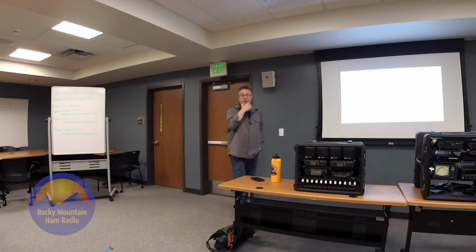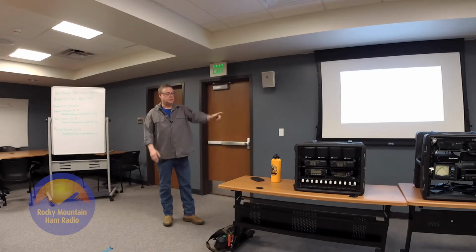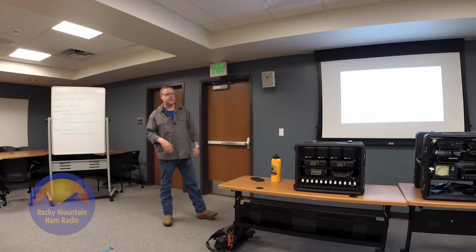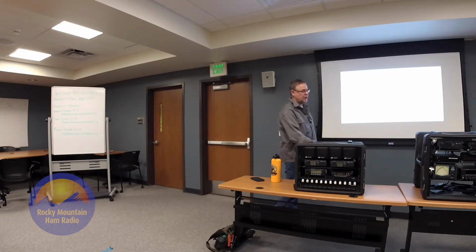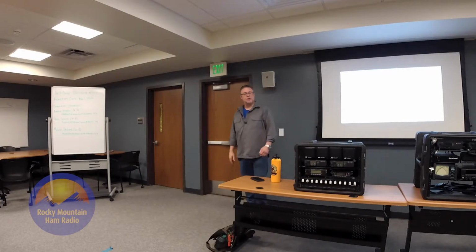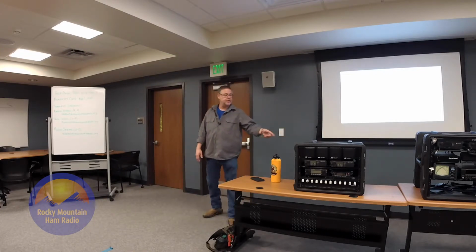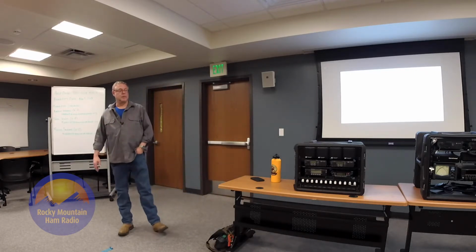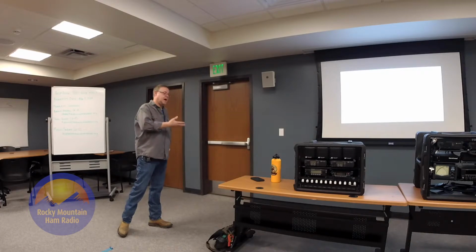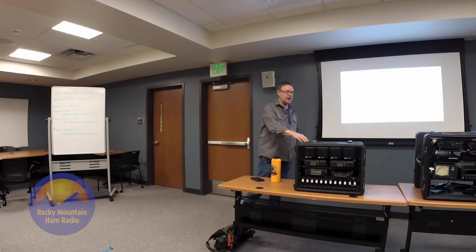A lot of them come with tripod stands that flip out, and you can set the panels at whatever angle. Cut off their connector cable or build your own, which is even better, and build a jumper cable that has your power poles or whatever your connector of choice is. Plug it into your charge controller. Your charge controller goes to your battery, and your charge controller then goes to your radio, and you're up in business. It will actually pull power off the solar panels if the solar panels can supply the desired requirements for the operations of the radio.